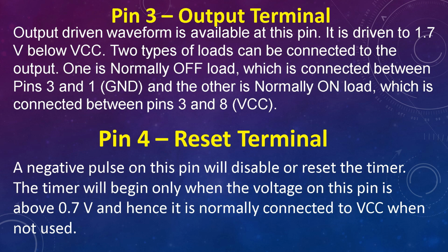Pin 4, reset terminal. A negative pulse on this pin will disable or reset the timer. The timer will begin only when the voltage on this pin is above 0.7 V and hence it is normally connected to VCC when not used.